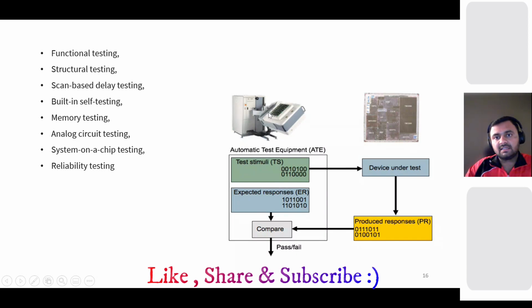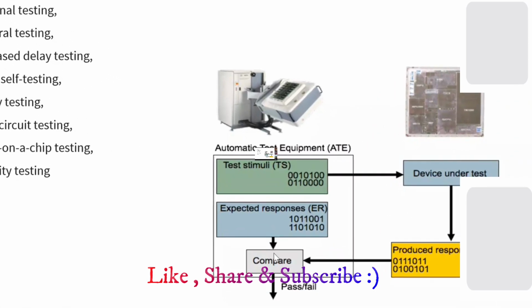Based on that, they will place your silicon here and apply those patterns, and they will figure out the response. There will be a comparator which compares your patterns: you put your pattern into the ATE, and it generates some response. So you need to compare that.